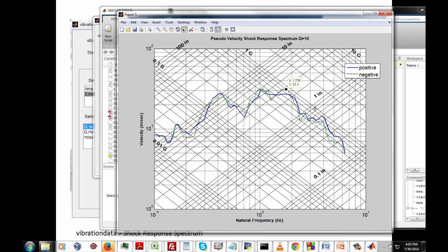Well, that's kind of sort of okay. It would be much better if they did a modal transient analysis in the time domain, but it's just the convention that we find ourselves in, that we're duty bound to pass along just a single equivalent static acceleration, which could then be applied as a body load in that static finite element model. Okay, so what acceleration would we then use for these hypothetical bridge structures to be constructed in California?